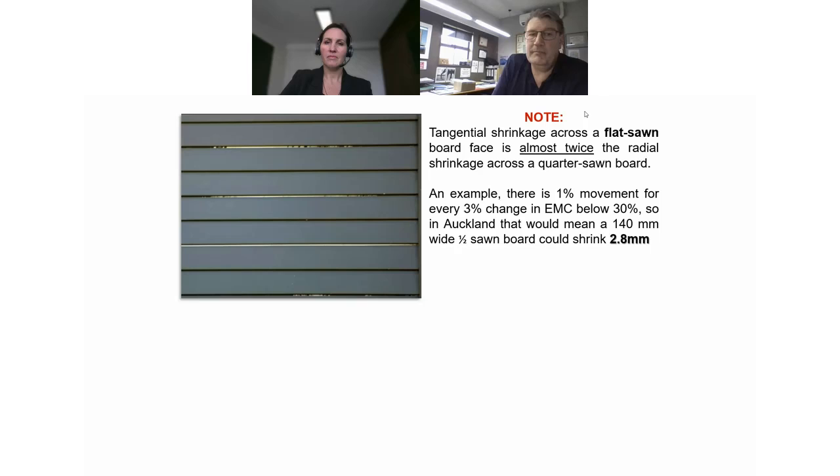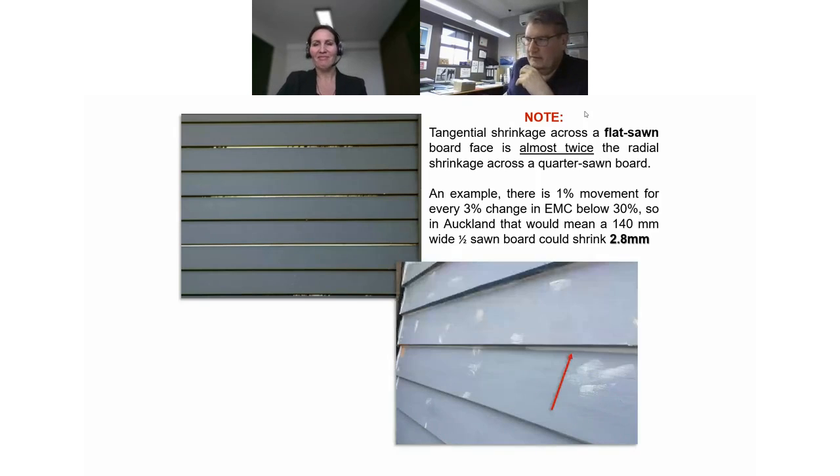So you think about it, all those old villas and buildings from the 1900s and 1800s, they had really, really massive weatherboards. Why do you think weatherboards have got shorter? Because moisture movement is a percentage movement. So the thinner the board, the less it moves. Just do the math.